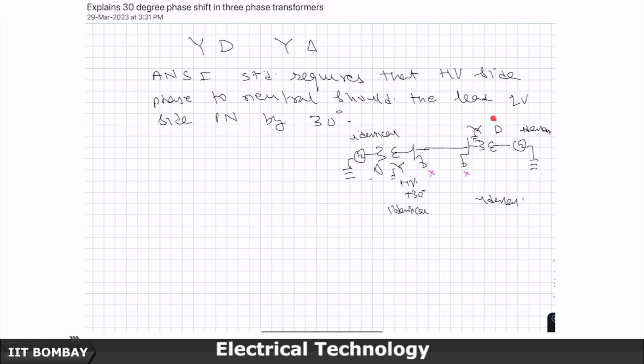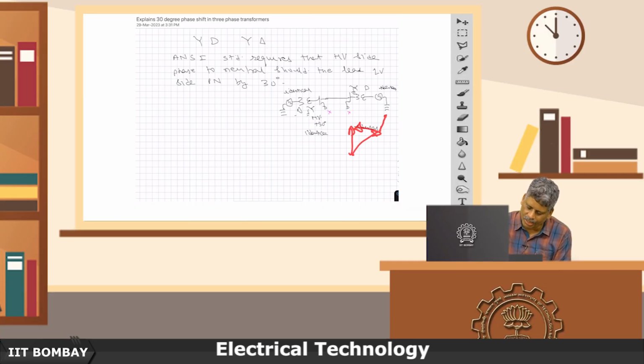If however you mess up and do not do this identical 30-degree phase shift on this side and on this side, then even though the magnitudes of these voltages are identical on the HV side, because there is a phase shift between them, a difference in voltage exists, and a current lagging by almost 90 degrees, 89 or 87 degrees, will be produced. That will create I square R loss here, here, here, and you will unnecessarily have a lossy system even under no load condition.